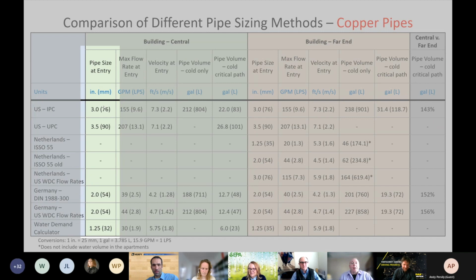Well, yeah, it has a lot to do with the pipe material. The Copper Development Association recommends the maximum velocity for hot and cold water, and even lower for a recirculating system. The PEX people, I know Uponor, I think they allow 10 feet per second on a cold and 8 feet per second on a hot. So it does depend on the type of material. And also the noise factor, like Miriam pointed out, that has a factor in it too, water handling.